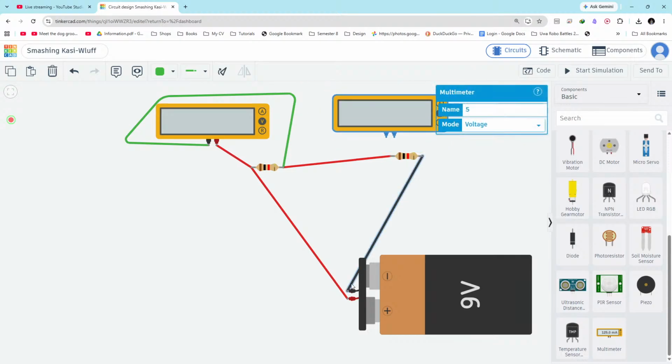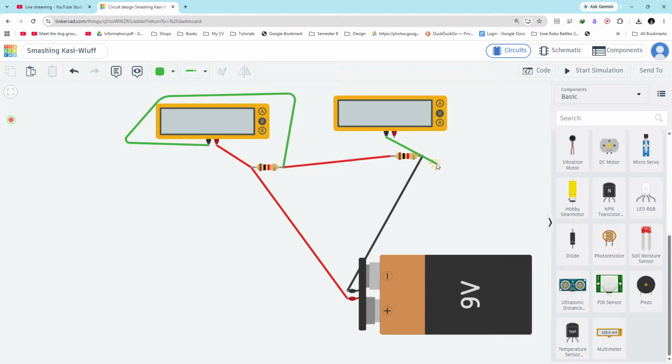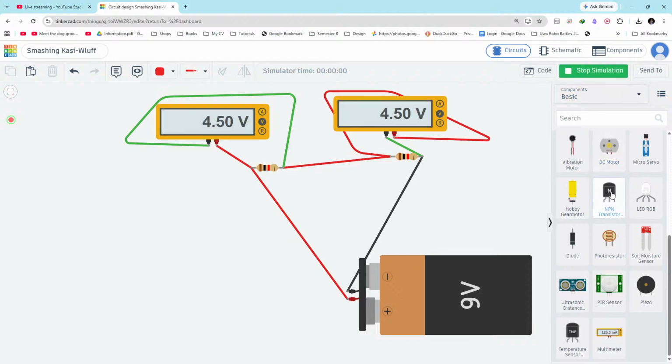As you can see that this wire is ground, which is negative, so we need to connect the negative lead here or here. It's the same, so let's connect it here, and we will wire a right wire to the left side of this resistor. Just to make it clear, I will move the wire from this side, okay? Alright, so let's start the simulation.